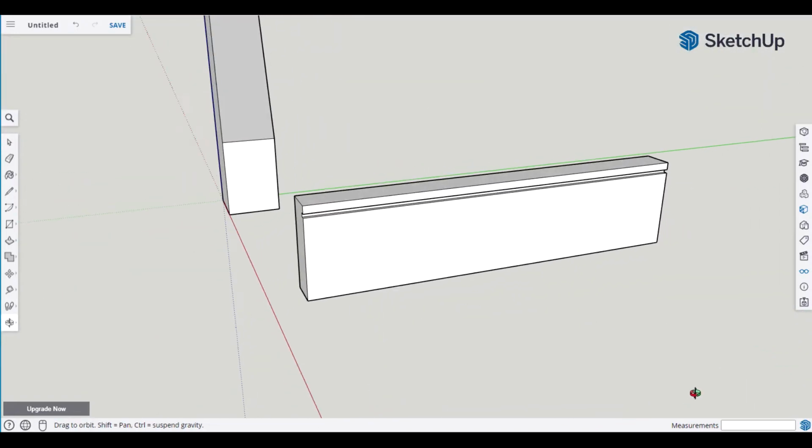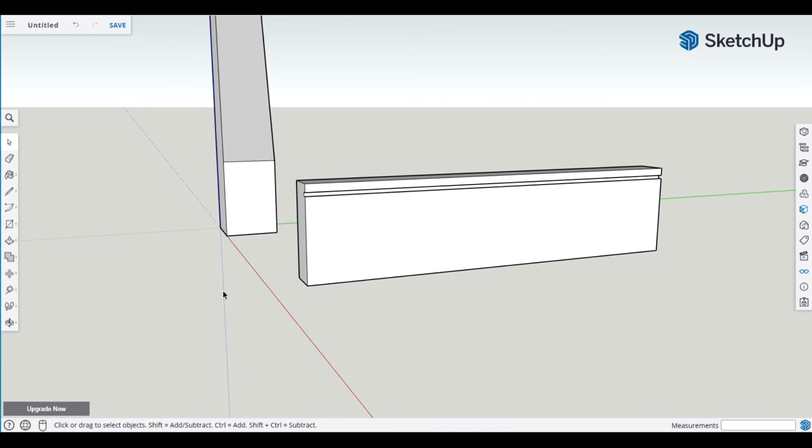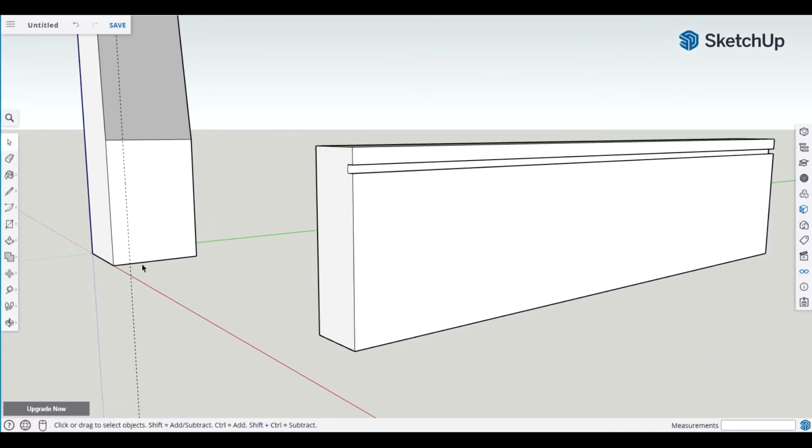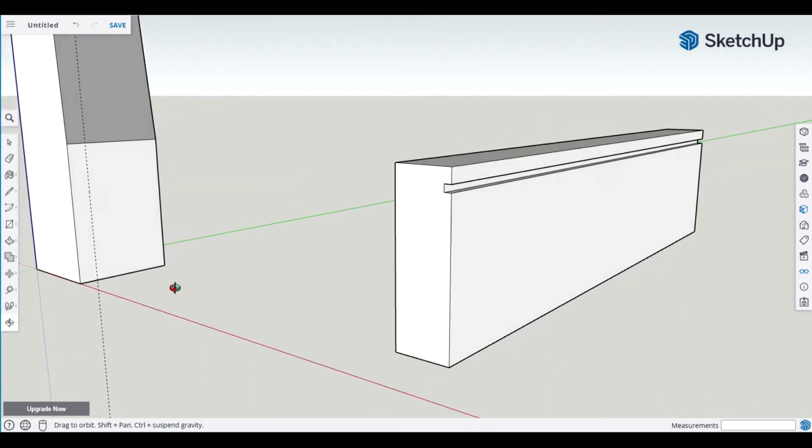Next is to swing this around and attach it to this leg. So we're going to go ahead and hit T because we want to measure in 3/8 of an inch. And then type in 3/8, enter, space bar, good. Let's make sure it's on the face. We're going to hit the over 2, yep, it's on the face.